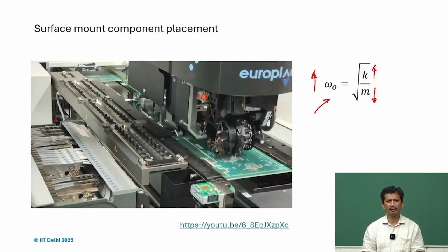So, we will try to learn how to get stiffnesses, how a single member can have different stiffnesses under different kinds of loading, under different kinds of deformations. We will also talk about how the parallel and series arrangements affect the overall stiffness of the system.